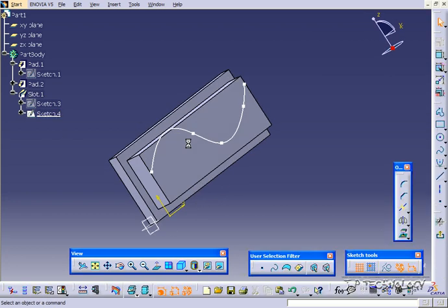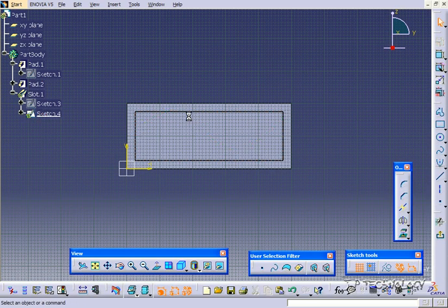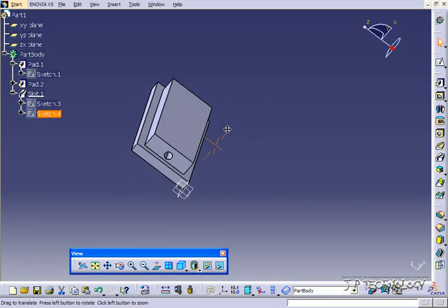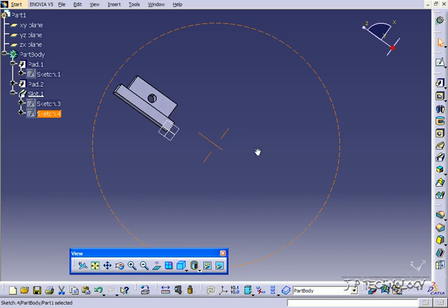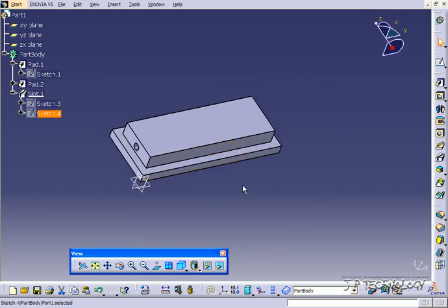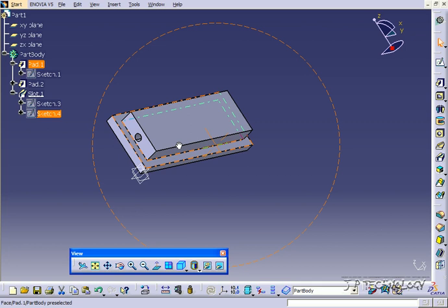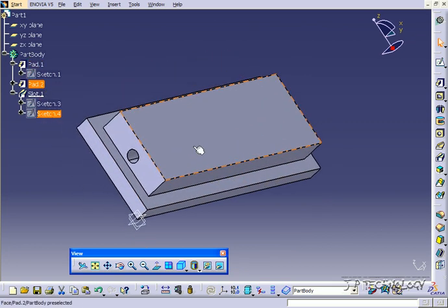Now if we double click on this, we're going to change this again, and we'll just make it go straight through. Go back up, and now we've cut the slot straight through. So by using the slot feature in an application like this with a hole, you're able to have your dimension of what the hole is going to be, and then draw out and say where it's going to go through, say, a larger block. So like a little pathway and everything for it.